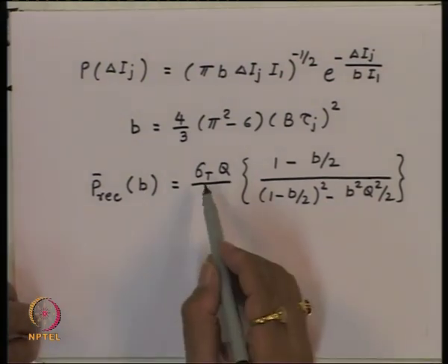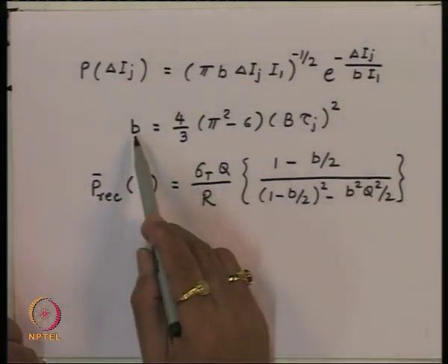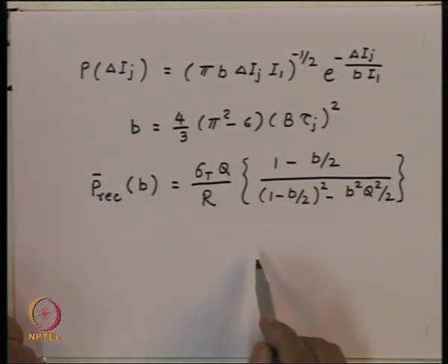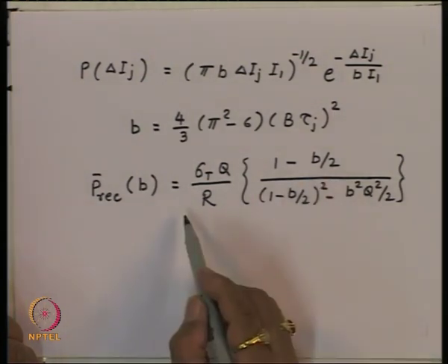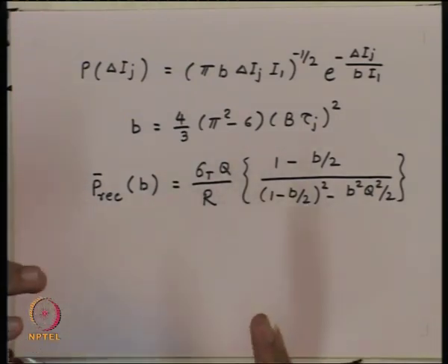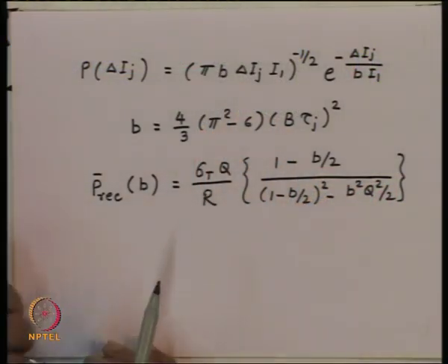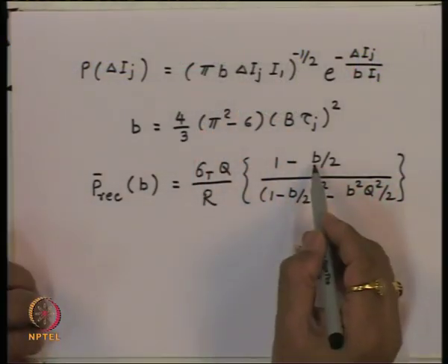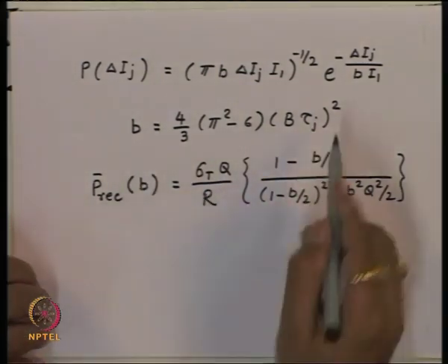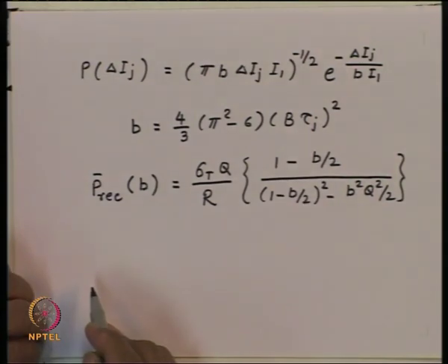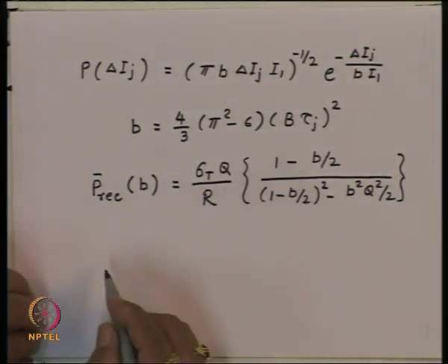So, again by substituting this quantity b equal to 0, we get the power required in the ideal situation. So, we essentially have now the P received corresponding to b equal to 0, that is the ideal condition, and now because of the finite value of b, which is related to the variance of the timing jitter, we get the corresponding power penalty.